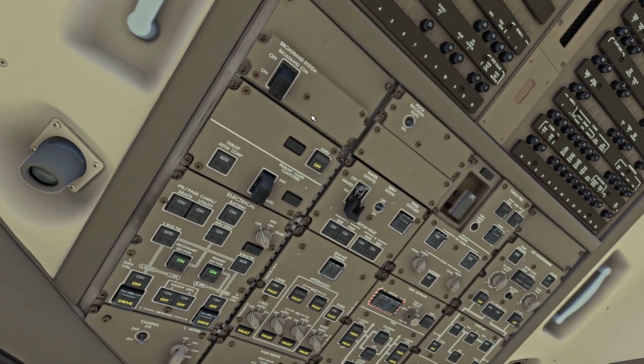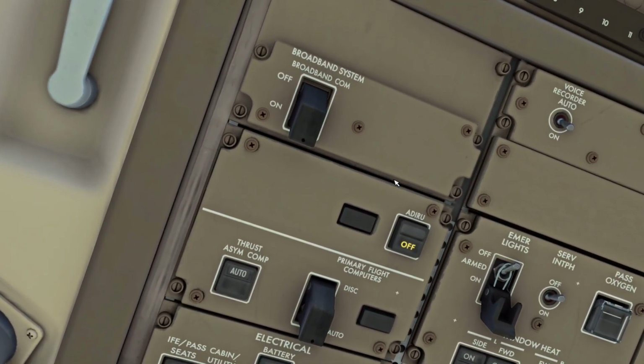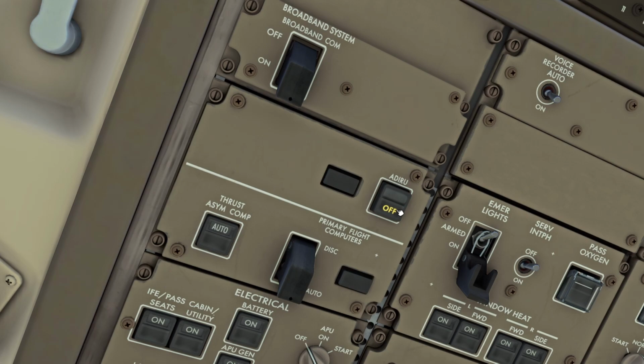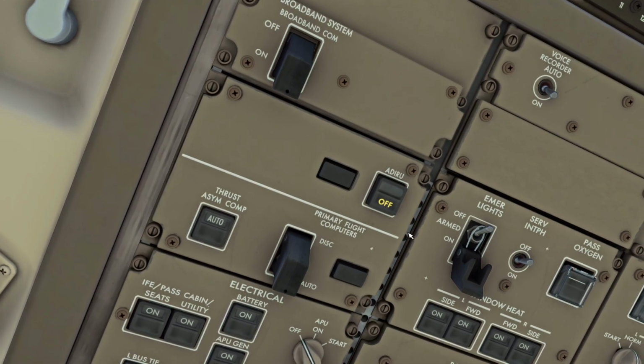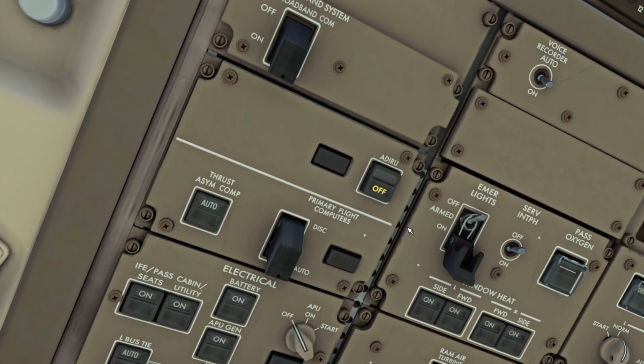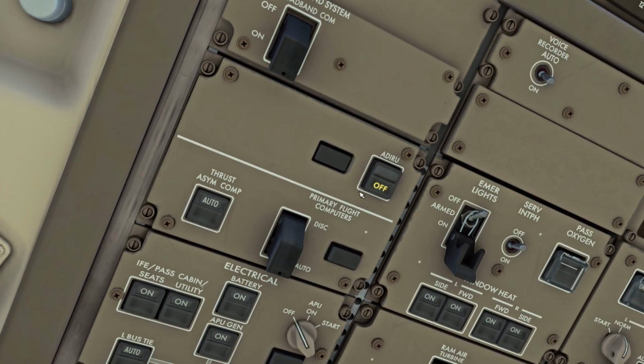Now the ADIRU is kind of the brain of the airplane in terms of determining its position in space and its attitudes, and it's good practice to realign the ADIRU system, because over time as you fly it builds up errors. Of course these errors are also mitigated by updating the position using GPS signals or radio signals from VOR stations or DME. But before every flight, it's good practice to give this a full realignment, and you can do that by making sure that the ADIRU switch has been turned off for 30 seconds, which by the way stands for Air Data Inertial Reference Unit.